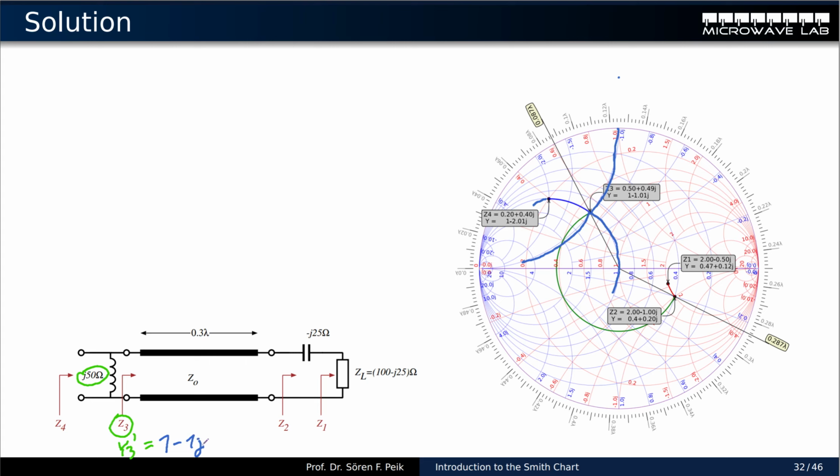1j. So one thing you always have to keep in mind is the upper half of the blue grid is now negative and the lower part of the blue grid is now positive. And often the negative values are not marked in the Smith chart because people assume as an engineer you know that. So negative red values are down here, negative blue values are up here because everything is mirrored. So this point here, my nice point, is 1 minus 1j.